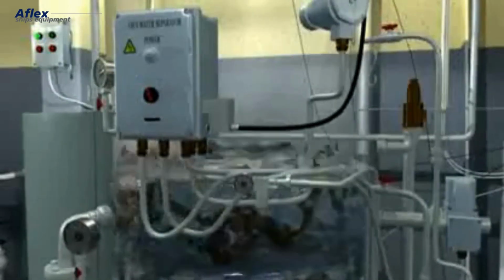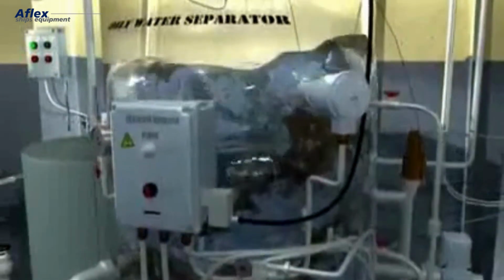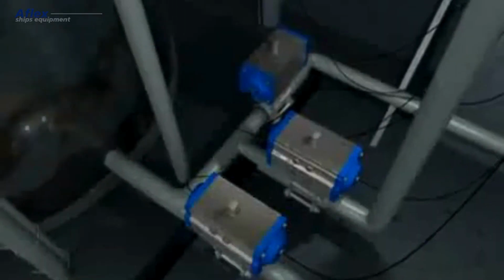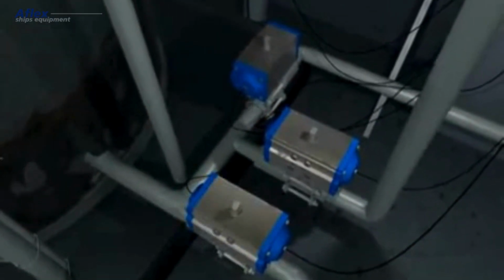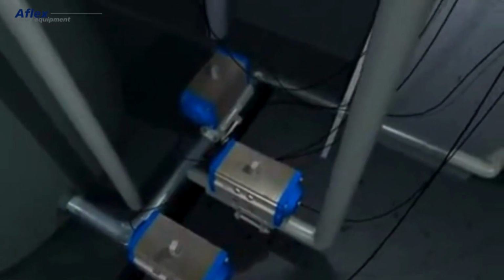The screening mechanism works based on the physical properties of the component substances, e.g., molecular weight and density. In water oil separation, the baffle walls in the coalescing filter divert the heavier oil molecules in one direction to a drain point. This liquid is then discharged overboard or redirected into the bilge tank in the event that the oil content exceeds 15 ppm.